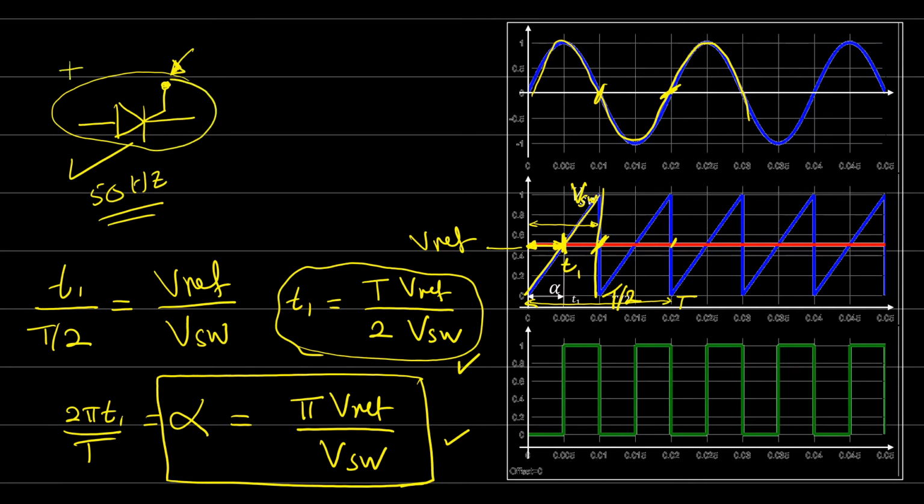Now revising the working principle for the thyristor, how the thyristor works. Now if we apply the voltage on the thyristor, it will be ready to work, but still waiting for the signal. If we send a signal to the gate, the firing angle, then the thyristor will start conducting like the diode. Even if we have positive voltage, even if this thyristor is in forward bias, without a signal it will not work. We have to trigger the gate.